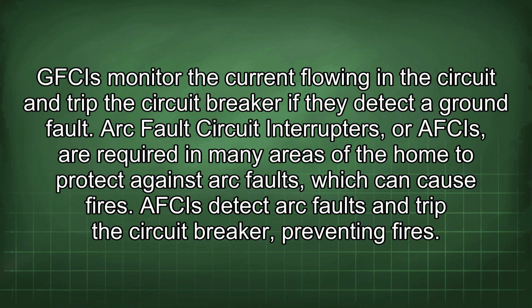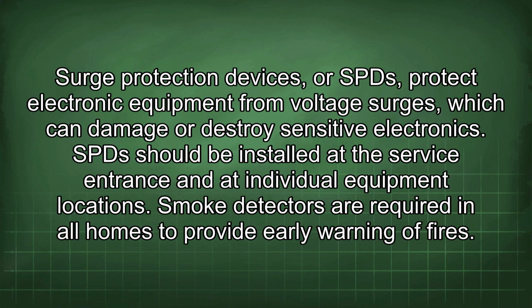Arc fault circuit interrupters, or AFCIs, are required in many areas of the home to protect against arc faults, which can cause fires. AFCIs detect arc faults and trip the circuit breaker, preventing fires. Surge protection devices, or SPDs, protect electronic equipment from voltage surges which can damage or destroy sensitive electronics. SPDs should be installed at the service entrance and at individual equipment locations.